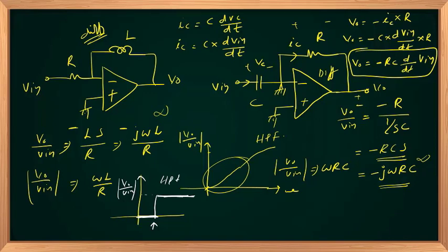Remember, for your high pass filter, you will have a lower cutoff frequency, omega L. In these two circuits, the lower cutoff frequency is not defined. We have to rectify the instability at omega equal to infinity by adding a shunt resistance across L or C. This will become open at omega tends to infinity, so you can place a resistance here.